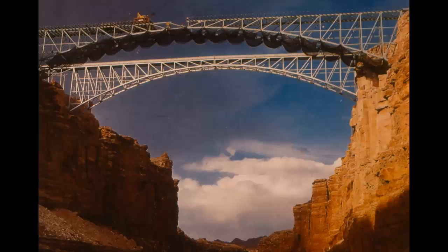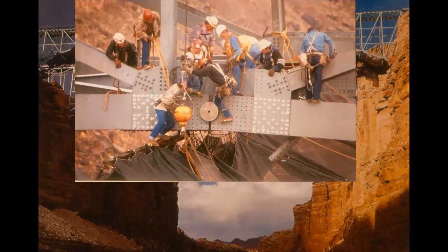Trusses use pin joints. The Navajo Bridge over the Colorado River was built by Kramer of Wisconsin in the 1990s. The pin joint at mid-span allows the two trusses built cantilevering out from the canyon on either side to be joined at mid-span without restraining relative rotation.